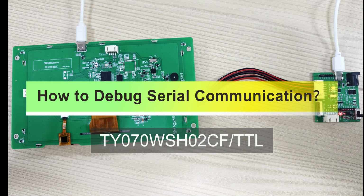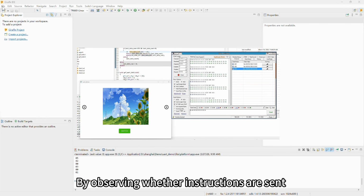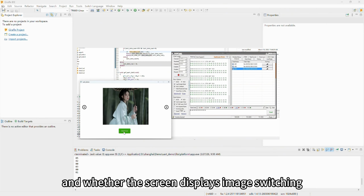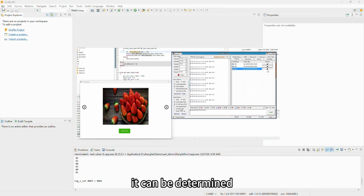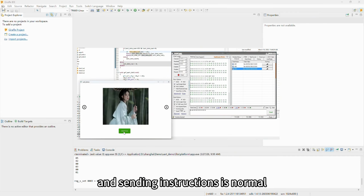This video explains how to debug serial communication. The Uart demo program can switch images based on instructions. By observing whether instructions are sent when the switch button is clicked, and whether the screen displays image switching after sending the corresponding instructions, it can be determined whether the device's function of receiving and sending instructions is normal.